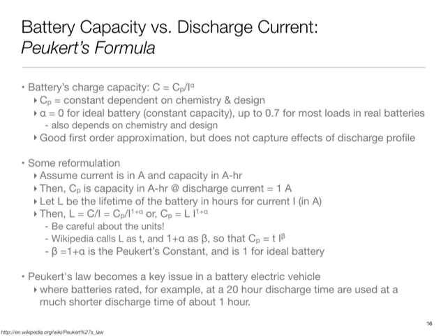Wikipedia has a slightly different definition. So beta, which is 1 plus alpha, is the Peukert constant, and beta is 1 for the ideal battery. This is the other way that things are presented, and alpha equal to 0 is for the ideal battery, but alpha is not what is called Peukert's constant, to answer your question. So Peukert's law has